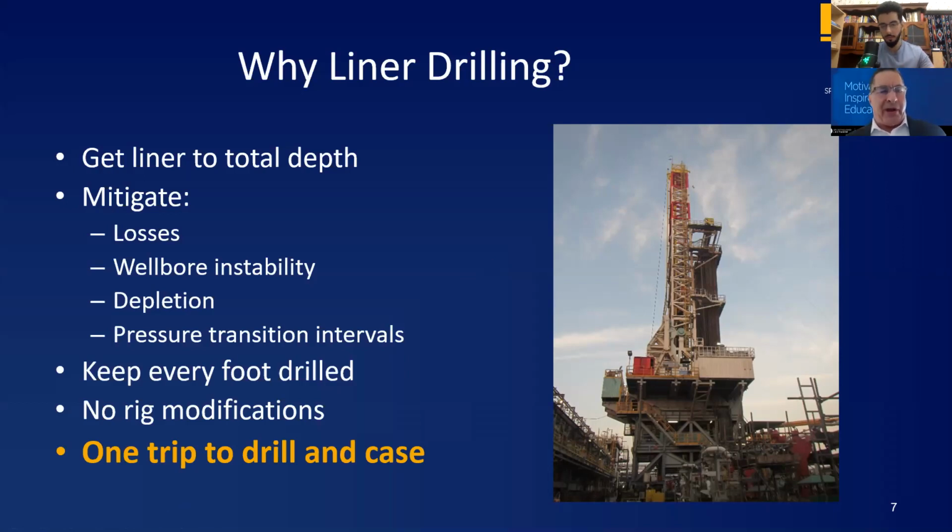So what operators are doing, they know they're going to stick the pipe. So why not drill a casing or a liner through the base of the pressured shale into the depleted zone, getting about 10, 20 meters into that depleted zone, and then you know the pipe's going to be stuck. In this case, it's not a bad thing. You've planned for it.